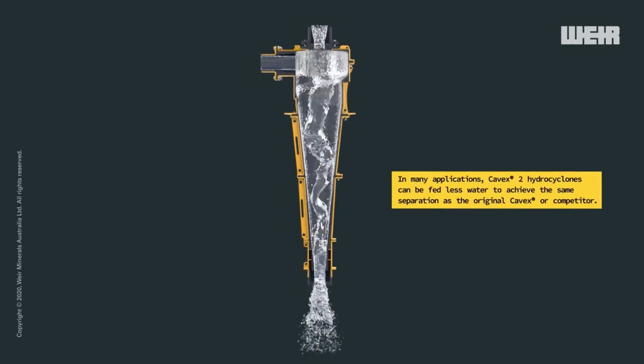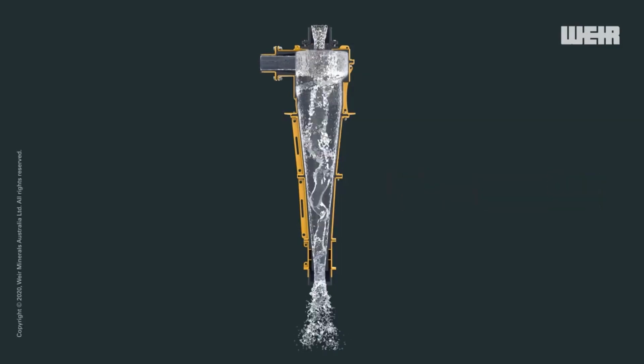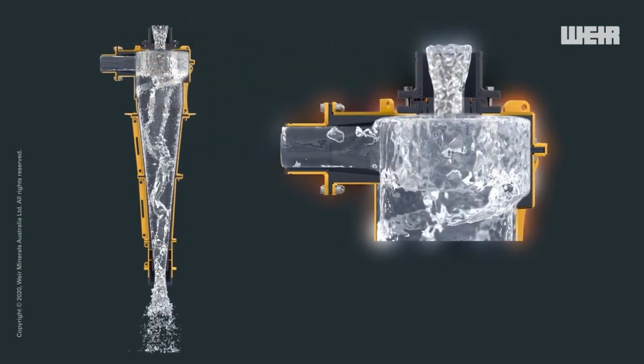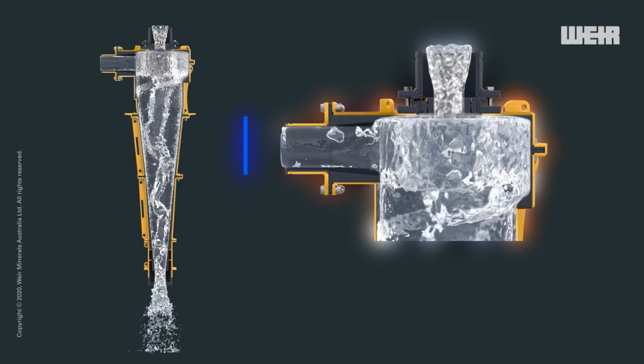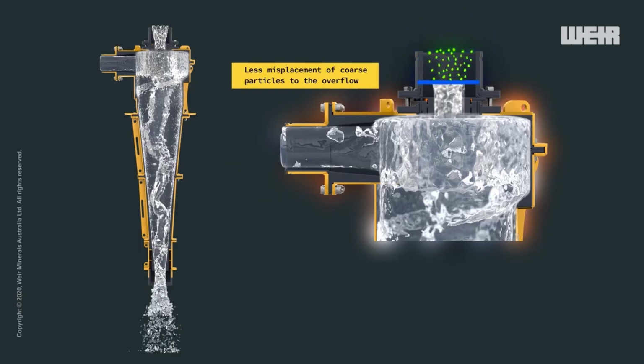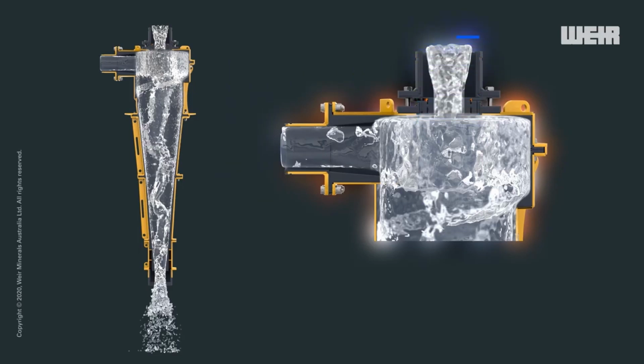If you don't have this vortex inside your hydrocyclone, you can't have classification. So in our lab we always start with pure water. We wait for the vortex to be formed, and after that we start to add solids. You can see over here that the guys really know what they are doing, and they definitely do a good job on this. And that's the apex.